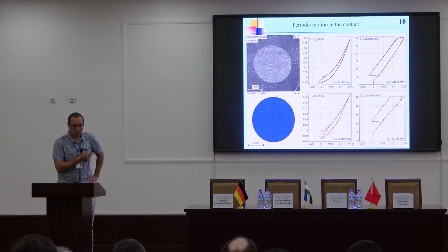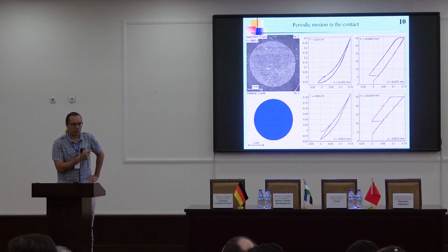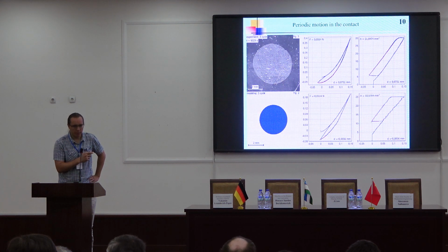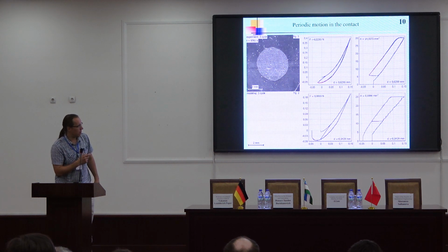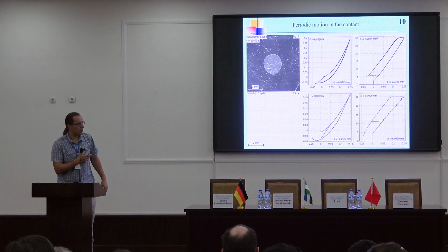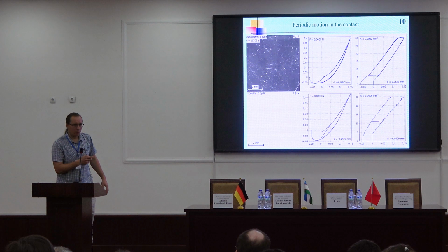layers of bigger thickness. Because of this, in experiment we have bigger values of the normal force. It's possible to use MDR, this method of dimensionality reduction, or the boundary elements method for thin layers, and we can obtain approximately the same curves with the same values of forces. But it was not the aim of this work. The aim was to show what happens in such a system.